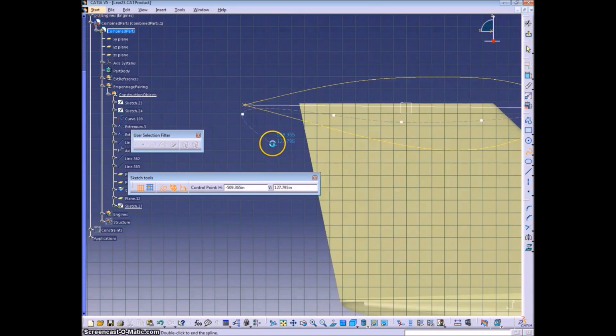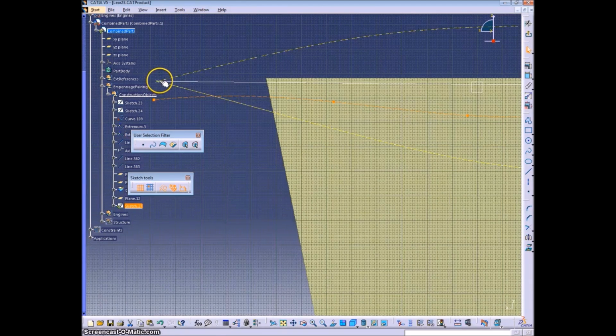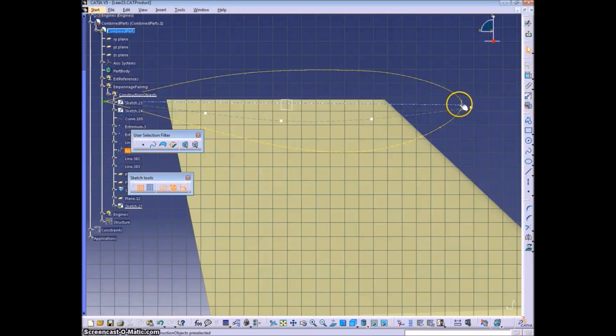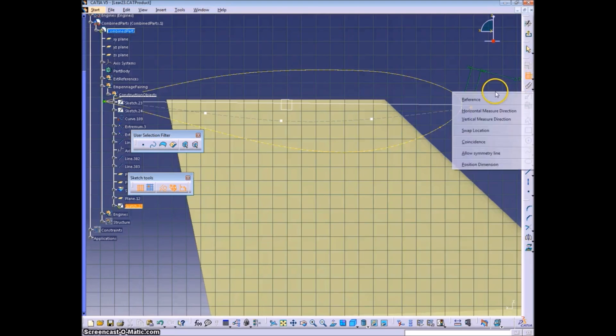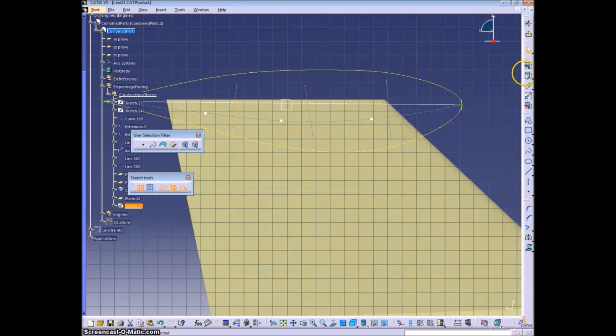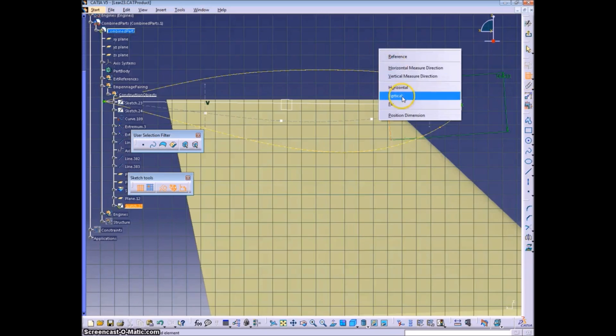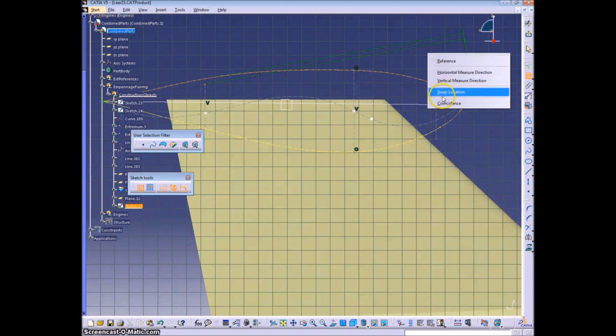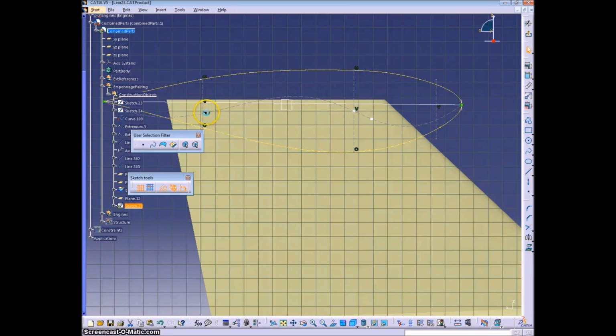And now creating our standard camber line contour through the middle here, using our lines with the spline constrained to the midpoint of the line. Standard practice at this point. Once we get this, we can extrude the line and then project the airfoil onto that.